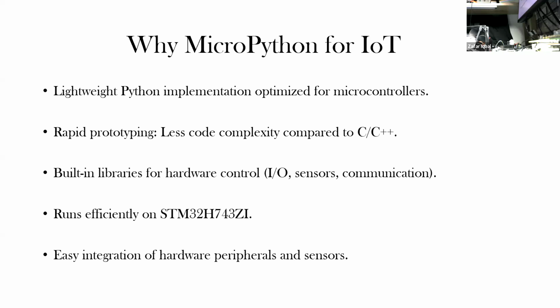Then again, it's very easy to integrate any library. For example, you might have used NumPy in Python. A custom version of NumPy named ulab is available for MicroPython. You can just download it, and you just need to build, because there's no need to customize anything. Just drag and drop the files in a folder known as user C module. You can build, you can flash, and you can run.